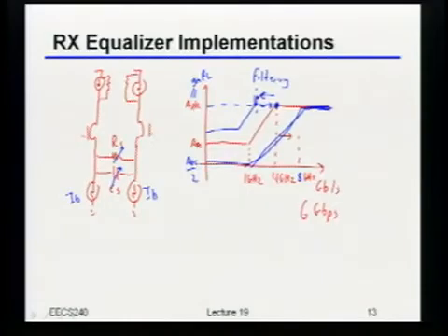If you put it too low, you'll actually be filtering out part of your signal. Okay? It always turns out what you want to do is really place it right in the right spot. In other words, right at the bandwidth that you're interested in. Does this make sense to everybody? Okay. So we talked a lot about this resistive degenerated equalizer, but so far I've only shown you